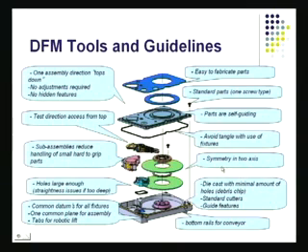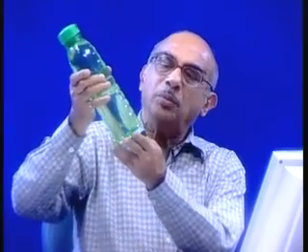And we've got some other considerations, like in this particular case, symmetry, die-cast material, and the bottom rails for conveyor. You've got to make sure that the product is able to ride the conveyor. That happens a lot. If you look at a bottle, right at the bottom of the bottle, you'll find some grooves, and those grooves are of no use to the user, the person who's going to be putting some liquid in this bottle. But this is a great aid when it's going through that filling line, and the bottle has to turn or stay secure so that the cap can go on. For that, we need those little studs there. That's something that is always done, in a way that makes manufacturing easier.